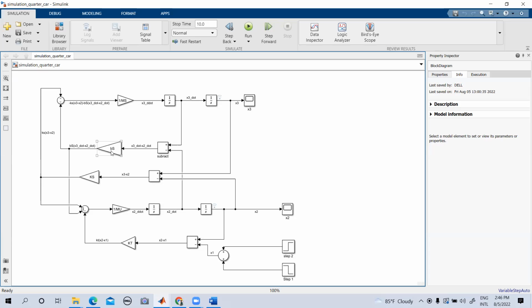mass, damping factor, the sprung spring coefficient, and the unsprung spring coefficient, right? And here this part actually corresponds to mainly the unsprung part or the tire part. And this part corresponds to the sprung part, right? So simply it's like the first half, the second half. So you can see how this is obtained.